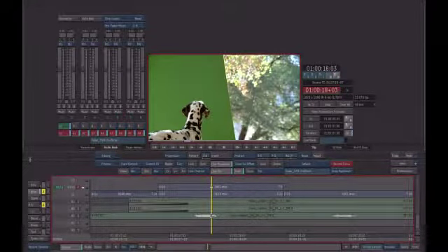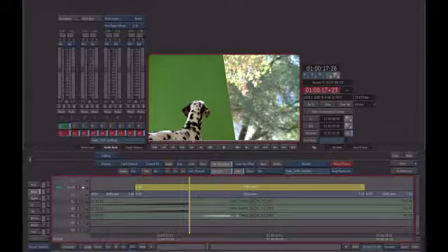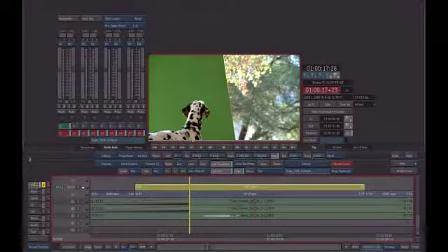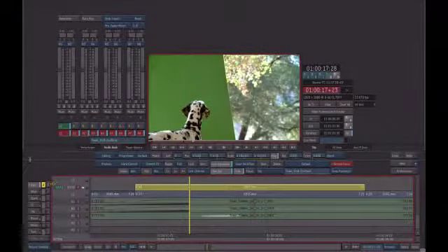Okay, so I've moved on to another scene, so let's keep going. So we've got some color correction going on. Now we want to do some keying. And chroma keying is something that we've all had to face. And the great thing about working in Smoke is it's got a great keyer built right into it. So I'll just start by adding a compositing effect here in the timeline, and I can start moving this layer around or whatever I need to do to it.